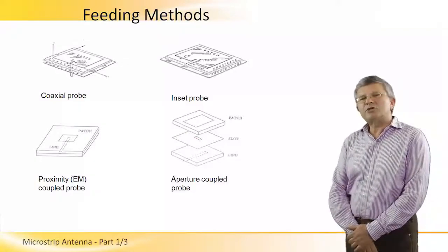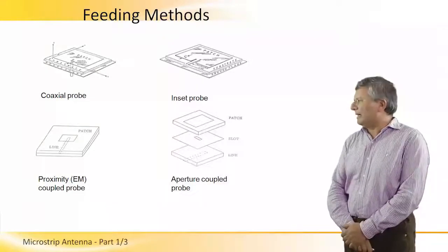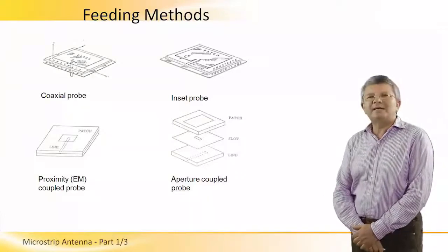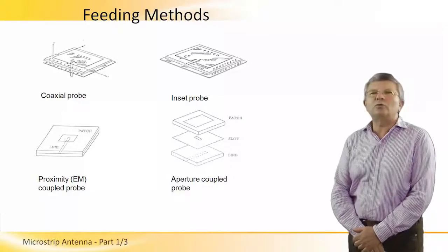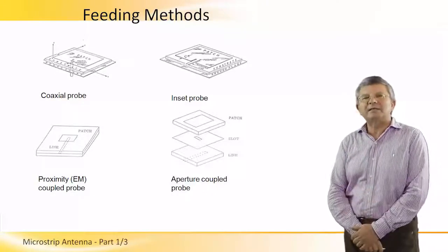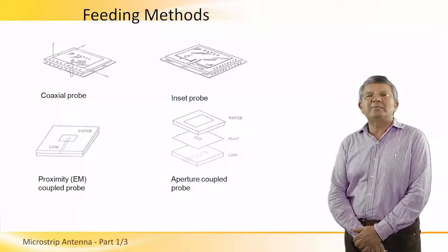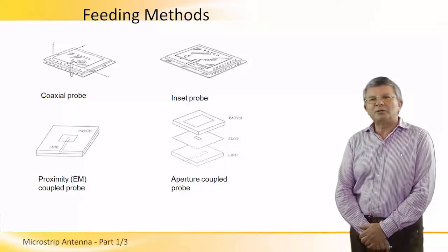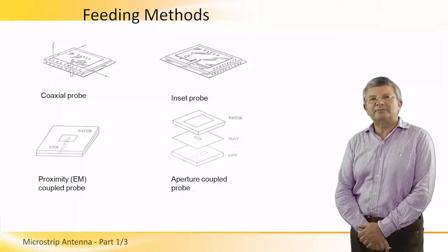This feeding is appropriate for multi-layer applications, in which we don't want to use vias from one layer to another layer, and therefore it is popular especially for multi-layer applications in which we integrate RF circuits with antennas.